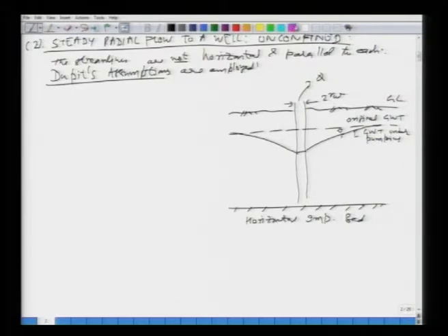All right. So, let us define all the parameters like we had done earlier. Everything we are going to measure from the center of the well. This is your capital R. You are going to take a couple of observation wells. So, let us say this is your S1 and this is your S2. The corresponding values of the height of the groundwater table are going to be H1 and H2 from the bottom of the aquifer, and these are located at R1 and at R2 from the well.